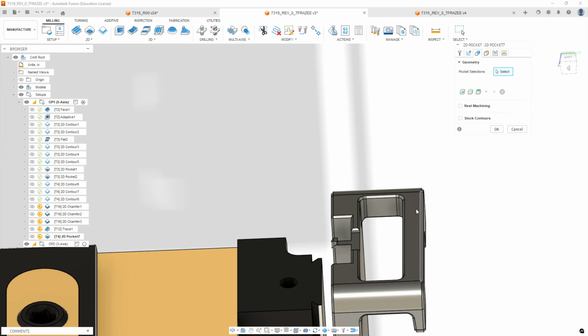We're going to go to geometry. We're going to select this surface right here. It looks like a little T. It should highlight 3 edges. We need to right click on this, hit edit, and change the extension method to closest boundary. We're going to hit OK.